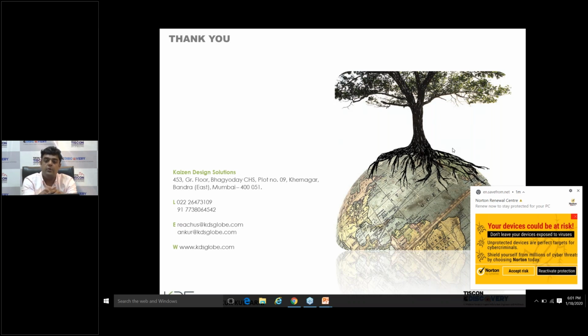But ideally, if you ask me, the Mumbai HRC guidelines also say that if the distance between two buildings is more than 20 meters, then you may not need to carry out all these studies, because 20 to 25 meters distance ensures enough sunlight and ventilation within the two towers. But again, it depends case to case. But yes, you can consider 20 to 25 meters should be the minimum distance between two.